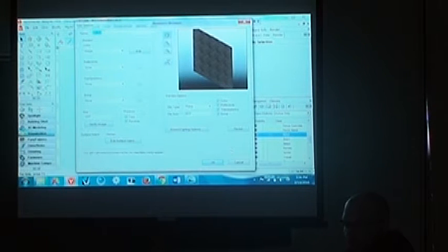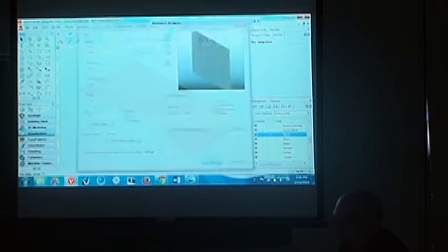Okay, so here I did 10 and here I looked at it at 50 feet. So you can see I set the image to 10 feet and I made the preview image 50 feet across. That gives me an idea, because I'm going to map that onto an extrude that's 50 feet across already. So that kind of gives me an idea what it's going to actually look like. And then I can hit OK.